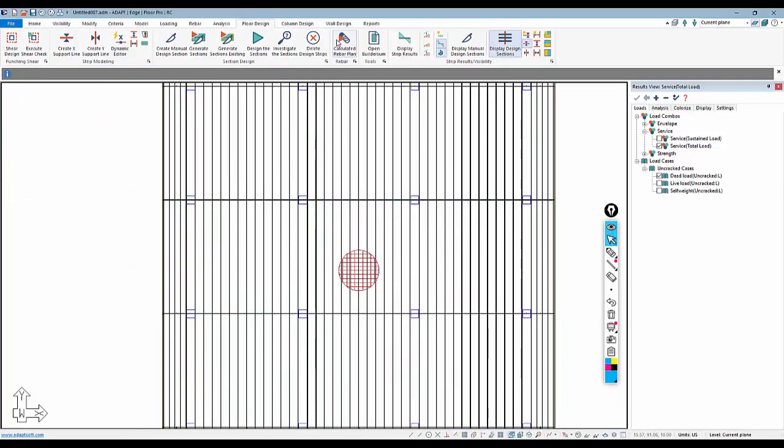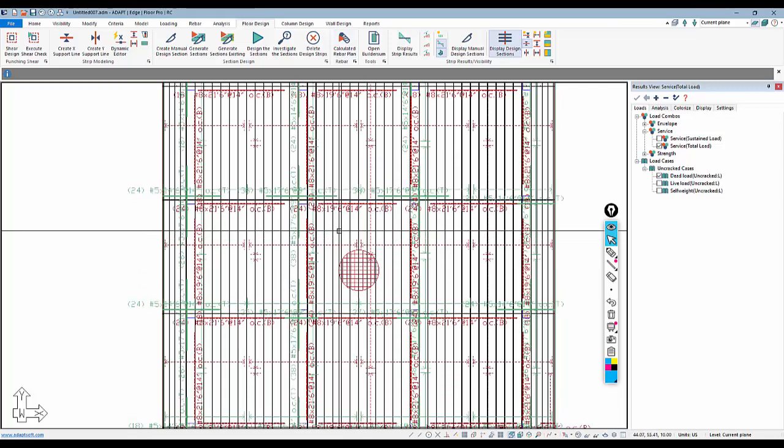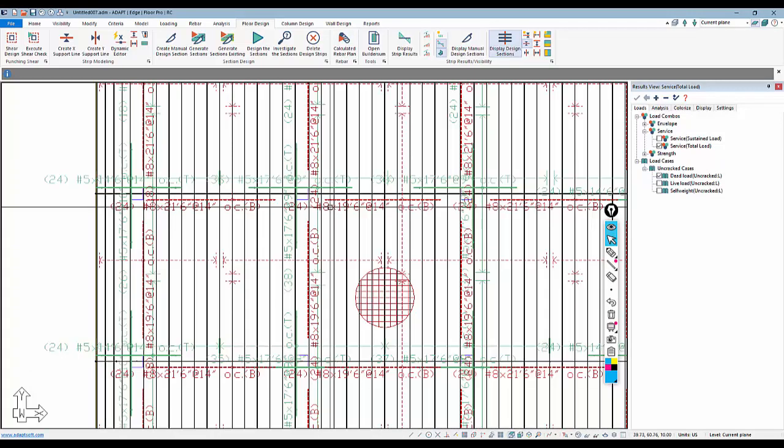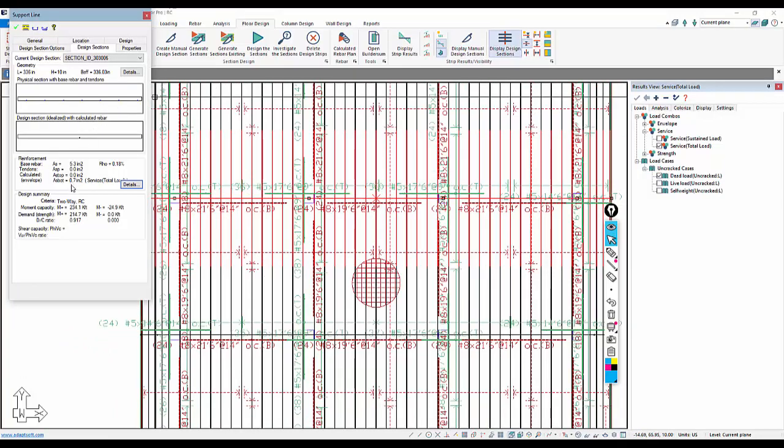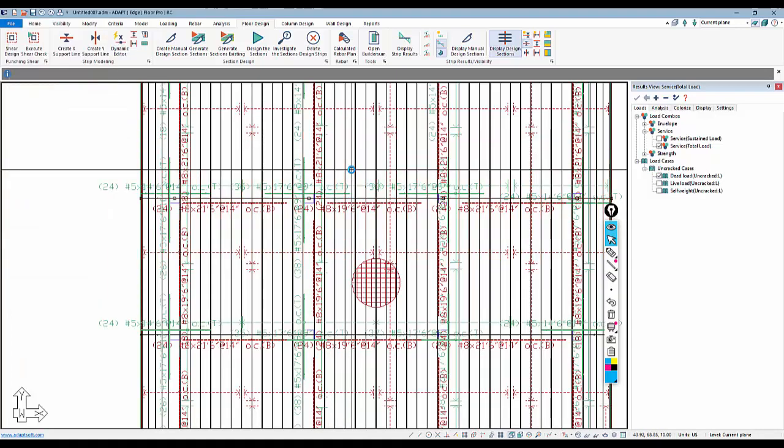And I will calculate the rebar again. Okay, now we need 24 again. So it goes right back to that 24. If I go back to the design cut, you can see we only need 0.7. We have 5.3 square inches per the base reinforcement. If we calculate the requirement, we still only need 6, so that's where the 0.7 comes from. But because we only added enough base and we still need a little bit of calculated rebar here, the program sets that trigger for checking spacing, and we get back to this 24 bars.